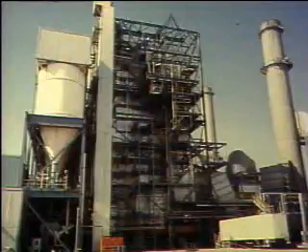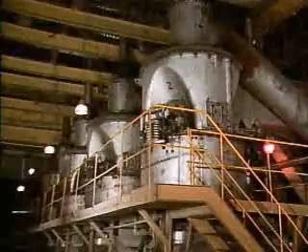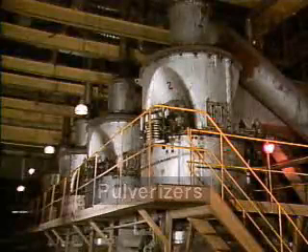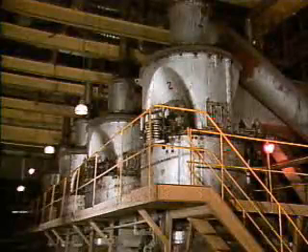We'll start with the fuel, which in our example will be coal. A conveyor system carries the coal from the coal yard to the plant. At the plant, machines called pulverizers grind the coal into a fine powder. There are several kinds of pulverizers, so your plant may use a type that looks different from this one. Once the coal is in the form of a fine powder, it can be delivered to the boiler. Let's look at an illustration of a boiler and its support systems to see how this can be accomplished.